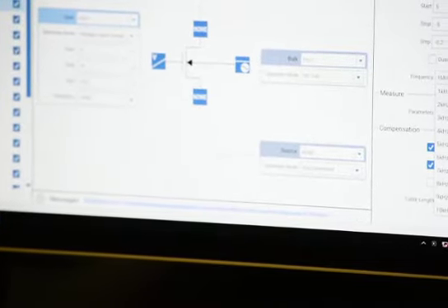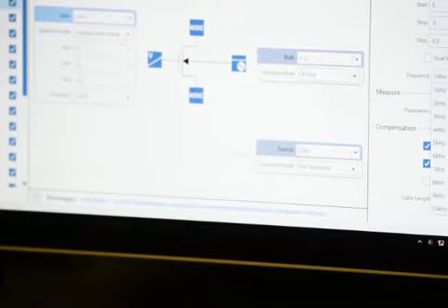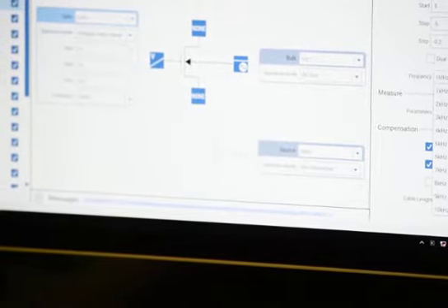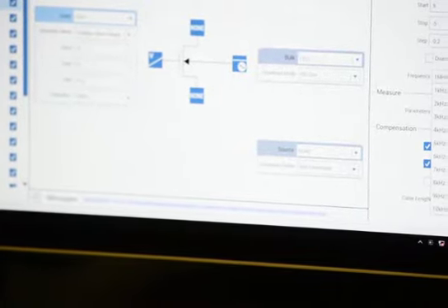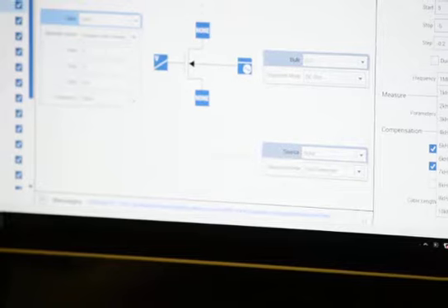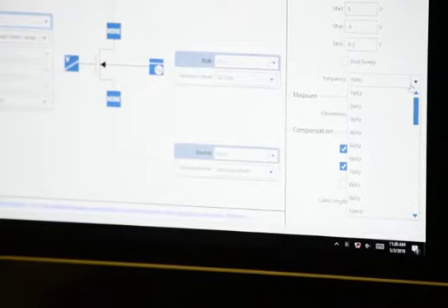Basically, normally you measure capacitance by applying an AC signal, right? With an AC bridge, yeah. But what you can also do is just apply current and then integrate that current to see what charge you put on there, and measure the voltage over time, or vice versa. And that's how you calculate the low frequency capacitance. So the transient response of the DC. Basically, yes.